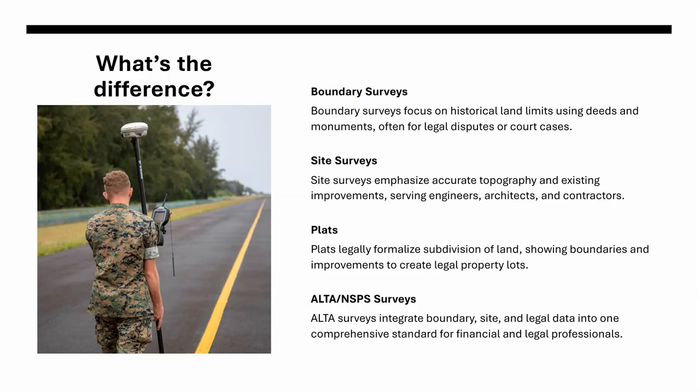And then we look forward to plats. A plat formalizes the work of both boundary and site surveys into a legal record, subdividing land, dedicating right-of-ways, and creating lots. A plat is both legal and physical. It depends on the boundary survey to define limits, and it depends on the site survey to show improvements and conditions. Together, boundary surveys, site surveys, and their plats all converge into a broader picture of land development.